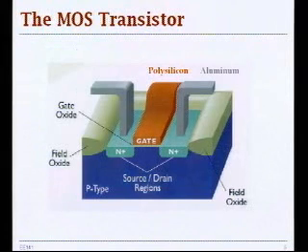So this is the bread and butter of today's CMOS processes, MOS transistor, and this is what we've discussed last time, and also a video in much more detail that talked about manufacturing process. So you have basically a transistor consisting of this polysilicon gate on top. You have source and drain regions, and then you have p-type substrate. That's the body of the transistor, and you have isolation for the field oxide.